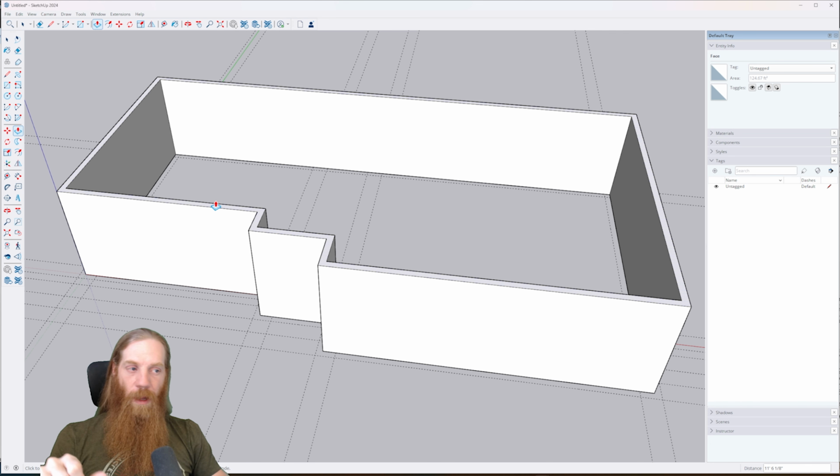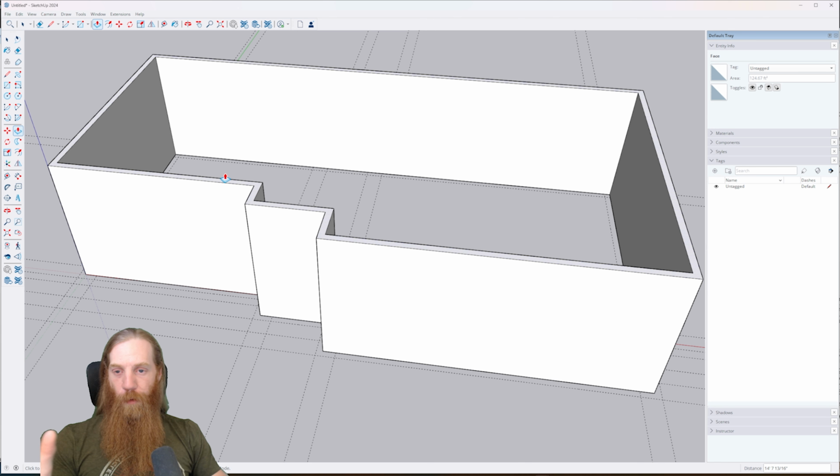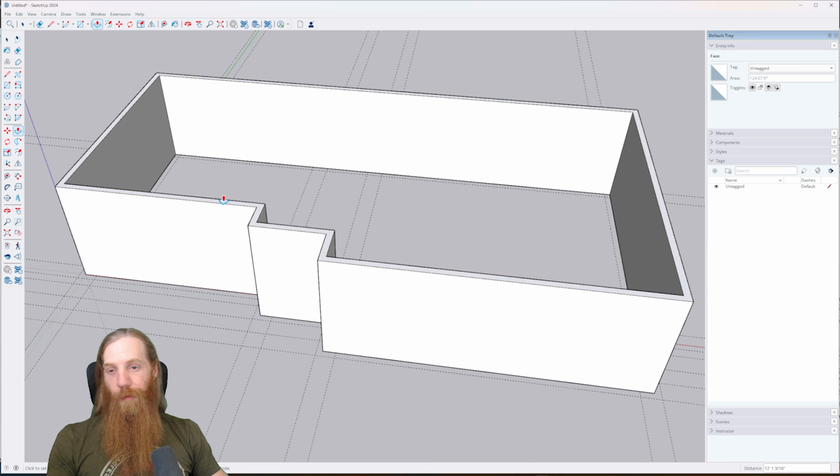this foundation wall. Now it's actually going to sit on top of a pressure treated sill plate that goes all the way on top of the foundation wall, and then you put your trusses on top of that. So technically there's another 1.5 inches there. However, you're going to have things like drywall for your ceiling that's going to take up another 1/2 inch or even 5/8 of an inch. So you could just go the full 9'4", or you can account for that plate height if you really wanted to. I think I'm going to go ahead and account for the plate height because I want to try and keep these studs under 8-foot studs.